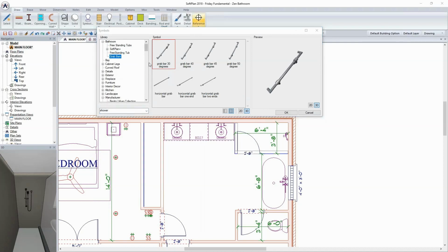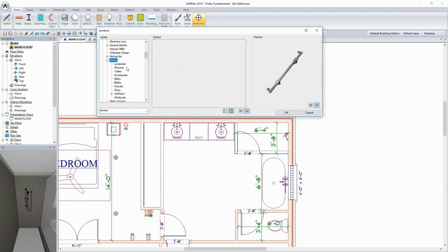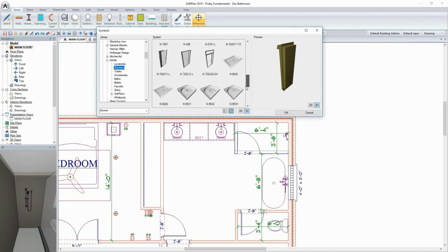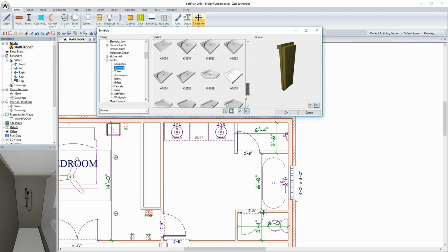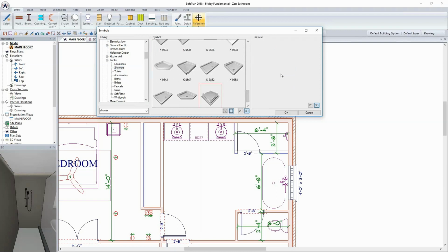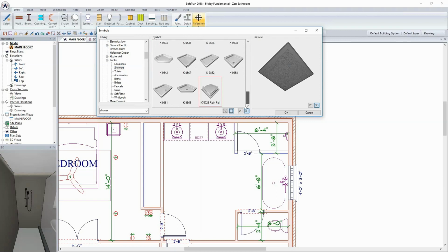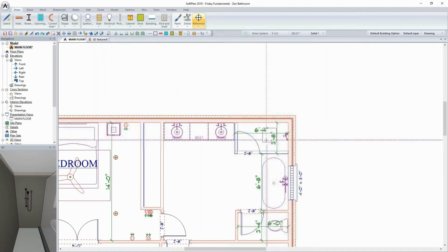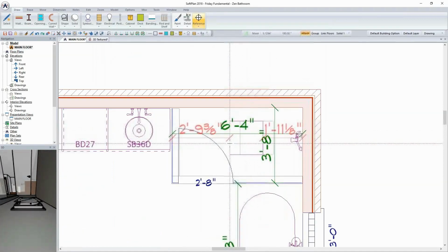Let me take a look inside my Kohler library. That is where I think I placed it. So I will go in through my Kohler, and I'm just going to go into my showers. And I'm just going to scroll down my list of shower options that are here. And so there's my rainfall shower head. In this case, I just actually went to the Kohler website and selected it. And so I actually listed it by the product code on here. And so now I can just simply click to insert and click to finish on this and move it into place.